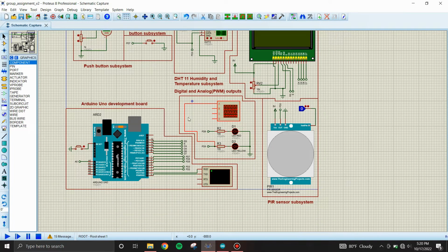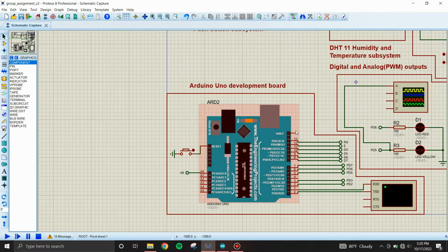We will be using an Arduino Uno board as the microcontroller in our project. The serial monitor will be used in our testing phases. As shown here, we will upload the .hex file of the Arduino firmware to the simulation.